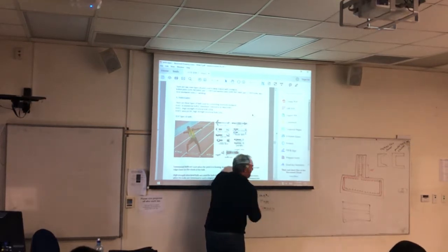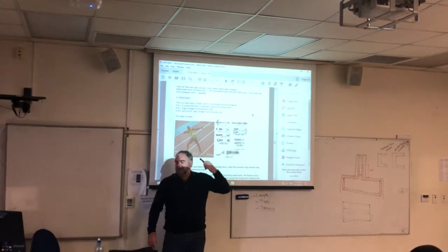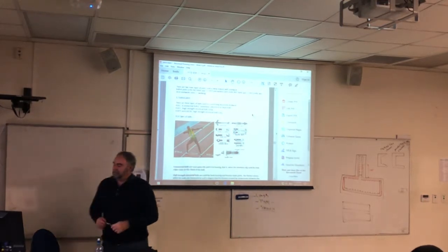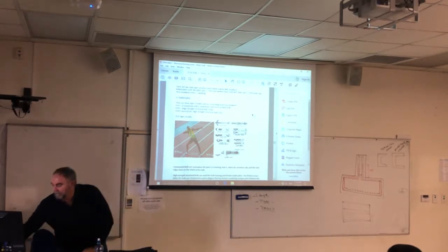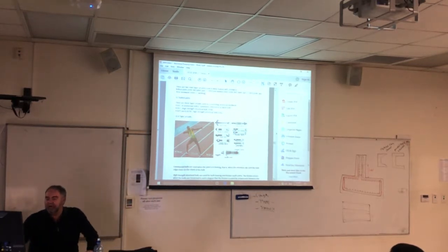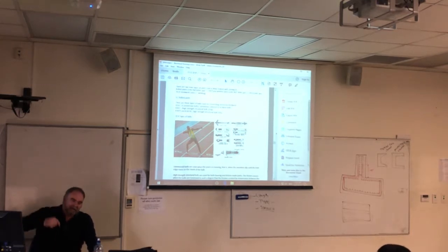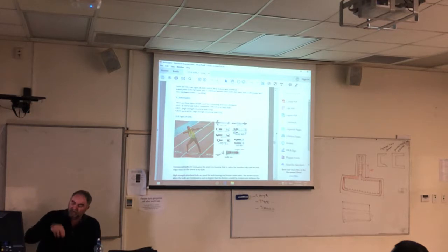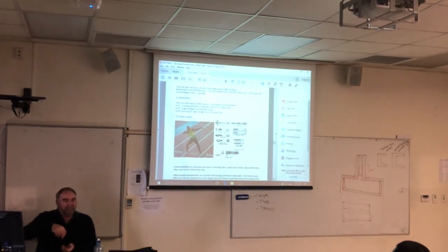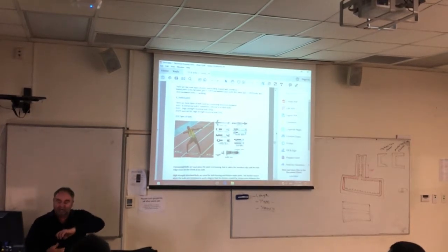The type of bolt is highlighted behind me on the screen, and I would suggest the bolts that go down into the handrail should be more like this one here with a head on it that's rounded. Alternatively, the bolts that go through the deck should be recessed into the wood. So you would drill a hole, recess it in, put your socket on top and tighten it up, either from the bottom or the top or both.